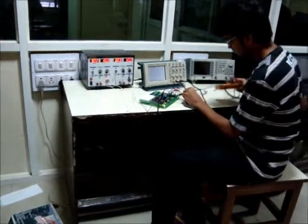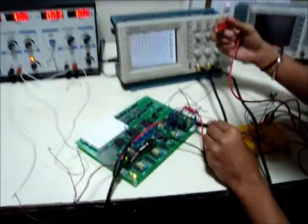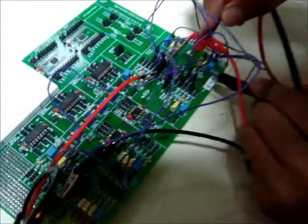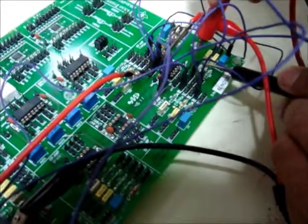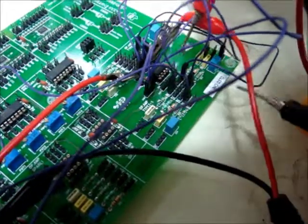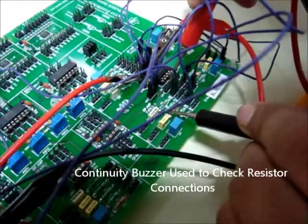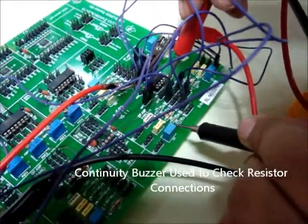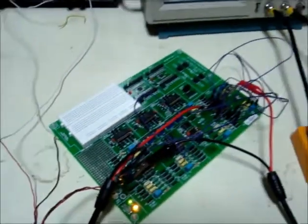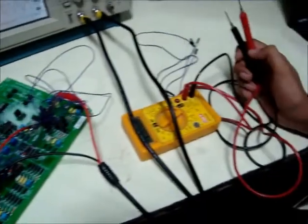One of the advantages that we had was that the Analog Starter Lab Kit provided to us by TI was very good. The connections were made using jumpers, which were pin to pin and hence very easy to implement. However, it was a little bit difficult to decipher the multiple connections that were present on the board. So we resorted to using the continuity buzzer of the multimeter to check the resistor connections, as shown here. Now we shall physically implement the function generator using the ASLV kit and see the results on the oscilloscope.